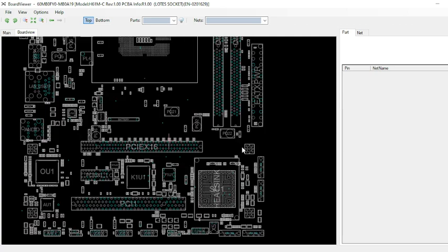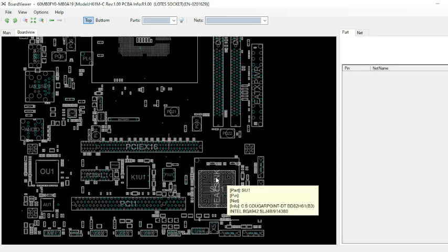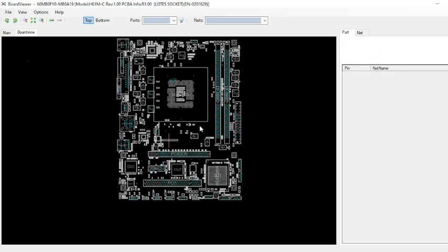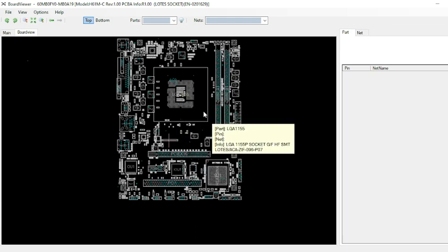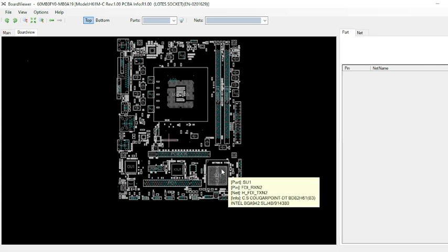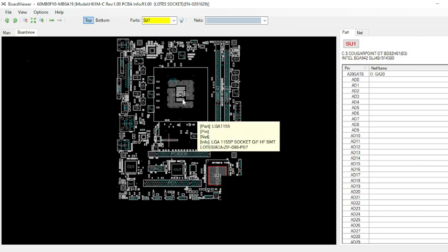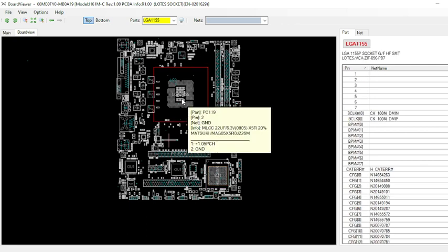After that, we are coming to our PCH. As you can see, this is a PCH architecture board. G31, G41, 915, 945 series boards have a hub architecture, and from this H55 we have PCH architecture. PCH means platform controller hub, which means north bridge and south bridge are combined together to form one bridge. And this is our processor socket where our processor will be connected.